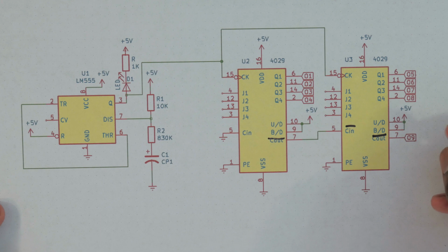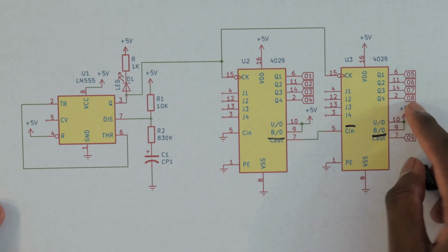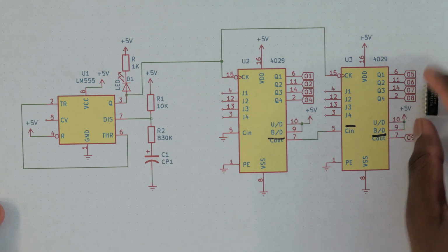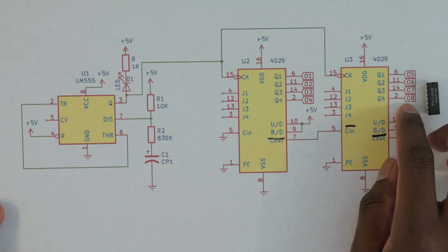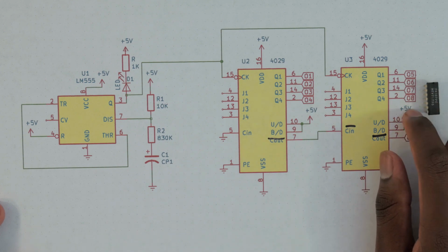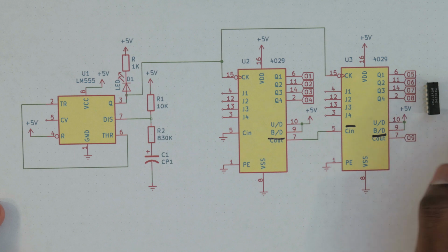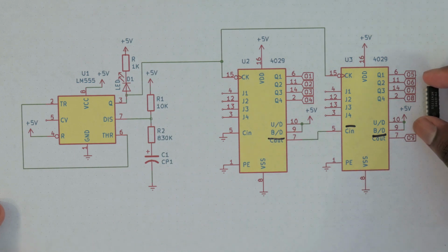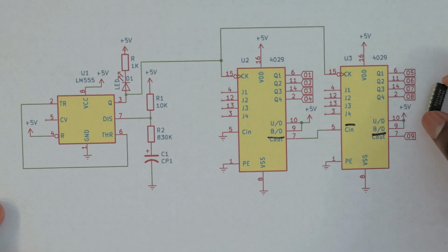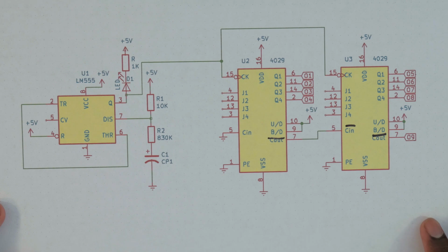So what I'm thinking is we can use the JK flip-flop on pin 8, and if we have the JK flip-flop clock signal tied to pin 8, that means that the 9th output would be on the JK flip-flop, as well as a 10th output on the JK flip-flop, which would give us our 7th and 8th bits that would go then into our EEPROM.